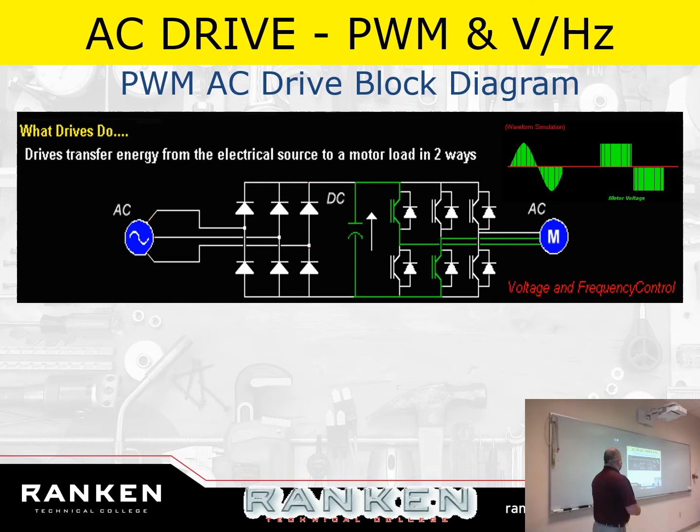The converter takes that AC sine wave, whatever the input voltage is. It doesn't matter if it's single phase or three phase. We have PowerFlex 40s in the side room over there, training tools that run off of 120 volts AC. 120 volt input, 230 volt three phase output. It doesn't matter what you put into them, you can get three phase out of it. That's why we use them. So the first part's called the converter.